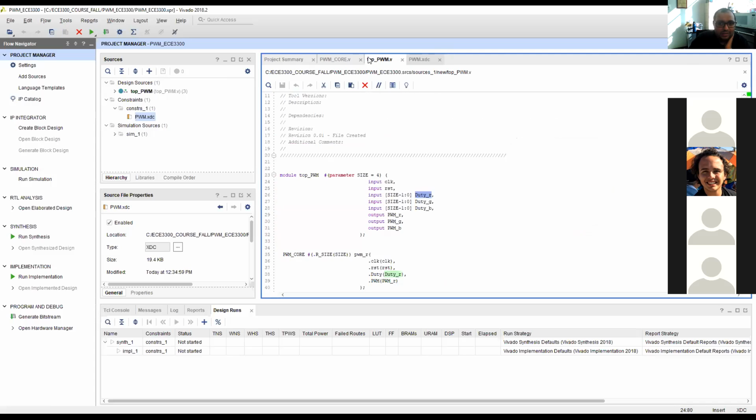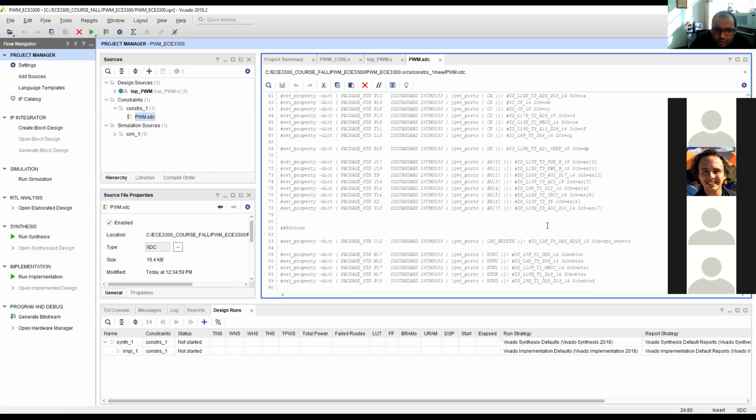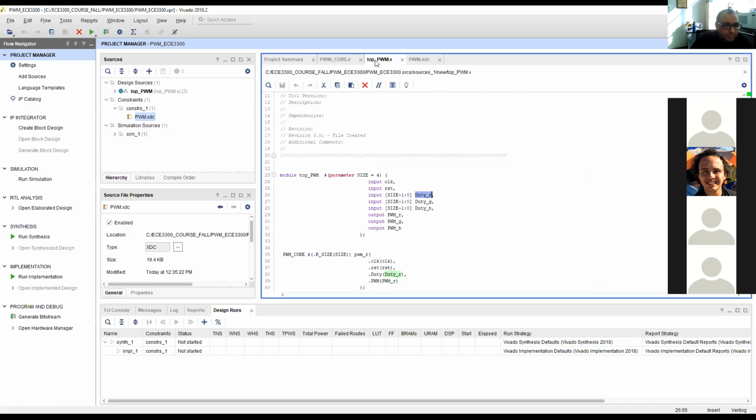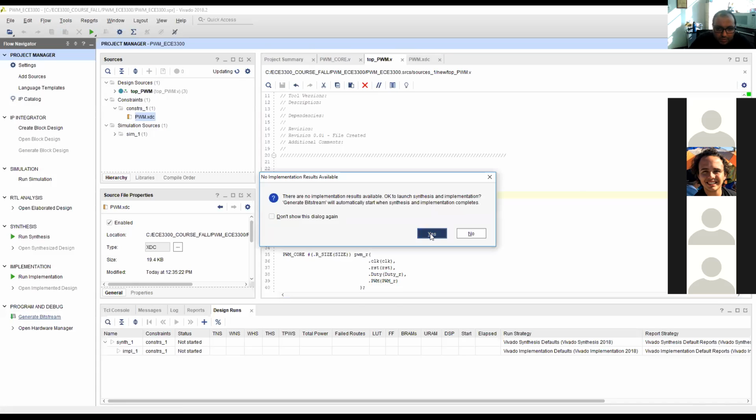Are we missing anything? Tell me. Eduardo, are we missing anything? Yes, reset. So where is our reset? We can take PTC as a reset. Anything else, guys? Okay, in that case, we'll just say generate bitstream and see what will happen.